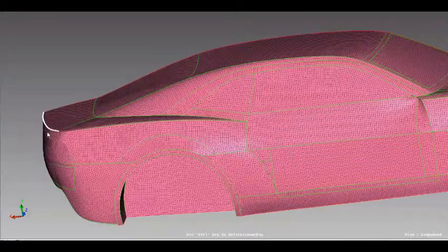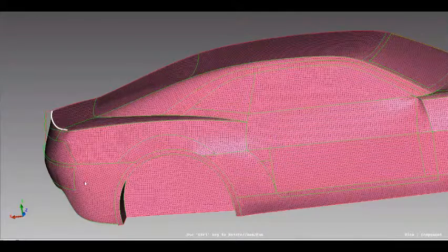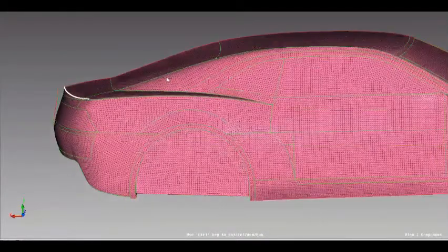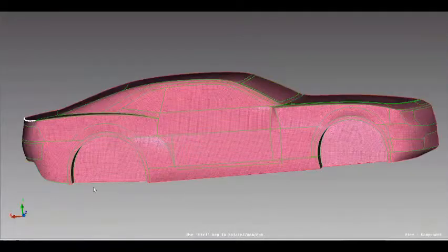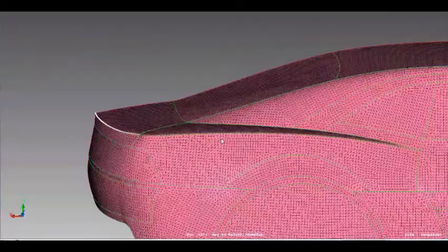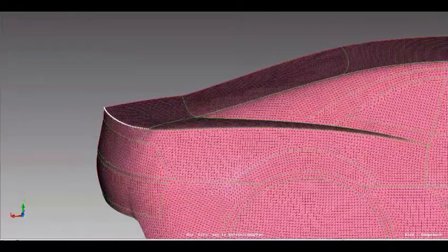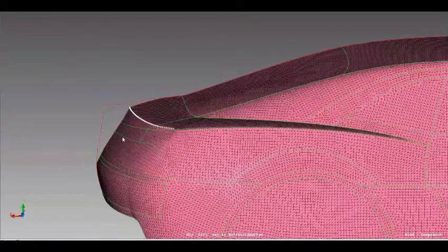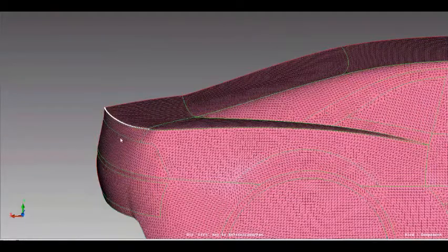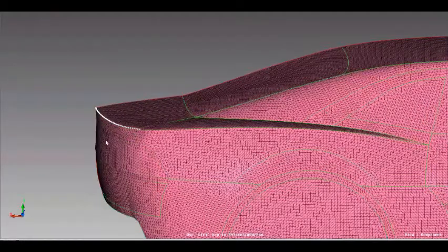So this takes the lower and upper bounds that we define in the parameter, and it animates on the screen for us to visualize, right? Here we're not really creating any upper or lower bound. We're just dragging the cursor on the screen to the left and to the right. Oh, so it's just showing us in which direction it is deforming. That's exactly right. The magnitude is not the actual magnitude. There's no magnitude here. We're just dragging it in each direction.